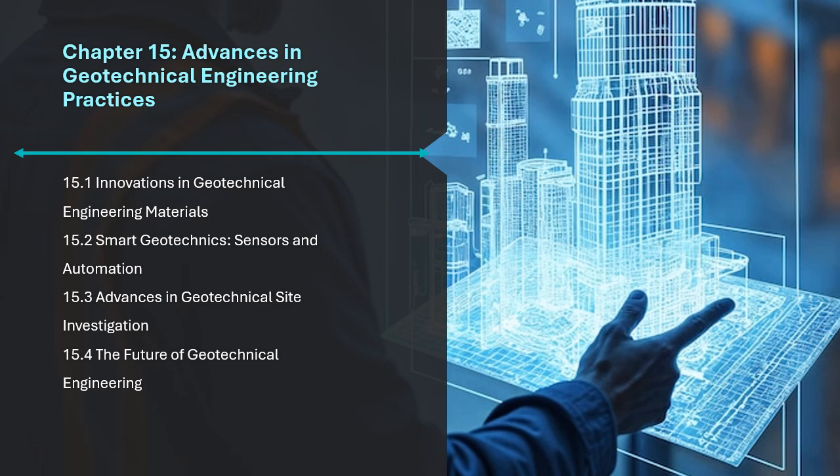15.3.1 Traditional Site Investigation Methods. Before delving into the new advances, it is essential to understand the conventional methods that form the foundation of site investigations. These include borehole drilling. Borehole drilling remains the primary technique for obtaining soil samples from the subsurface. The samples are analyzed to determine soil classification, strength, compaction, and other important properties.